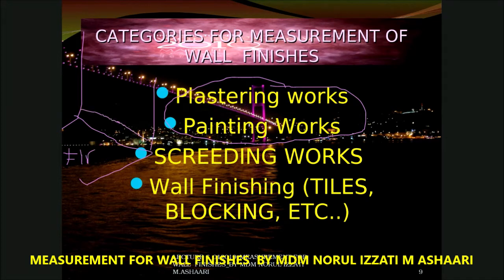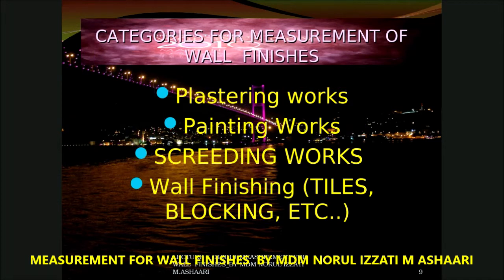On the top of this one will be your plaster and painting. If your floor is going to be finished with tiles, sometimes you can see the wall is also going to be finished with tiles, especially for the kitchen and the bathroom. That is where you have the screed and the block, or we call this one tiles, blocking, and the like.